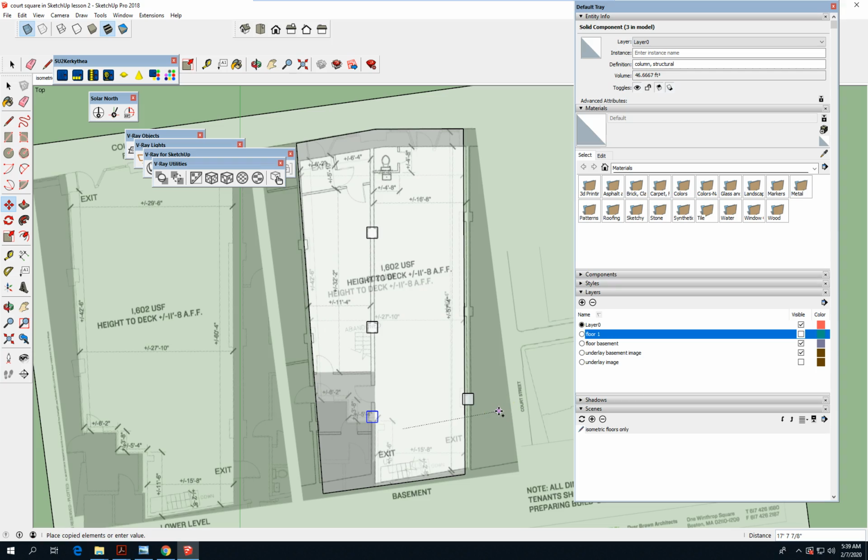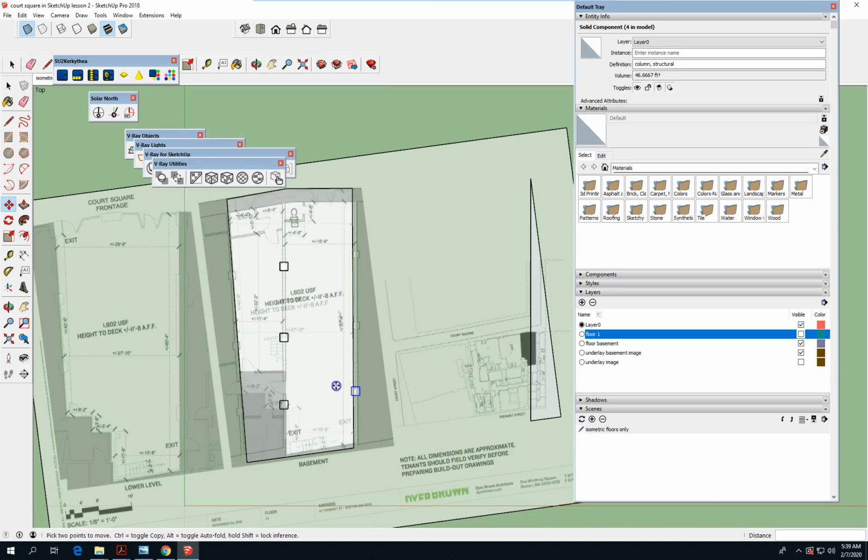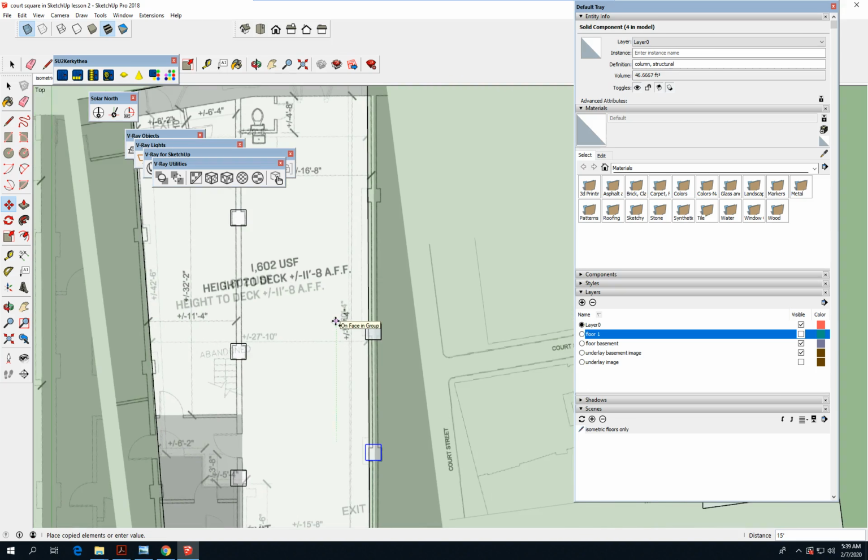You got to be careful not to snap to something, so let's see. Good. Top. Copy in green axis. Remember, we rotated this in order to work orthographically here. And again, in that direction, tap the control key, move copy.